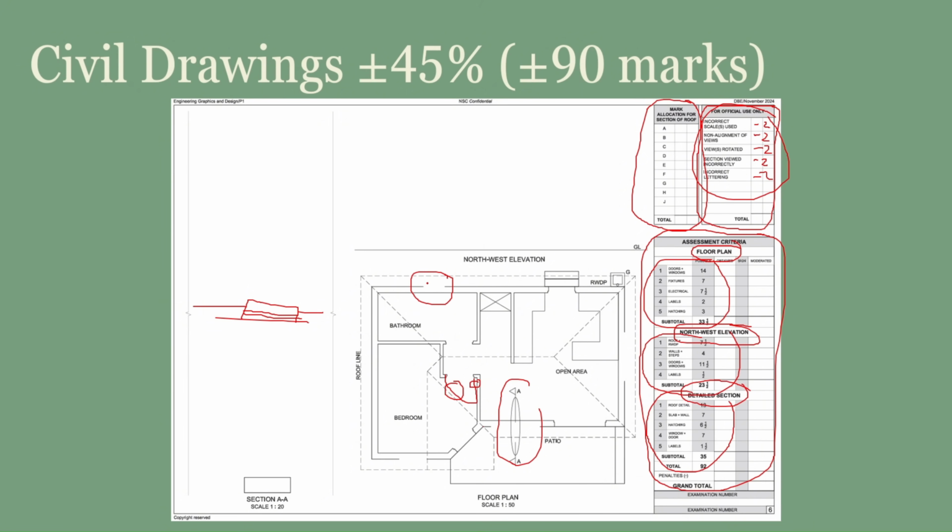So the window will usually be a bit smaller than the opening. What the markers usually look for is the little extension of the wall that you have added in. So just take note of that. That is a catch point. The opening that I gave you for the windows is usually bigger than the actual window size, either window 1 or 2, that you need to draw in.